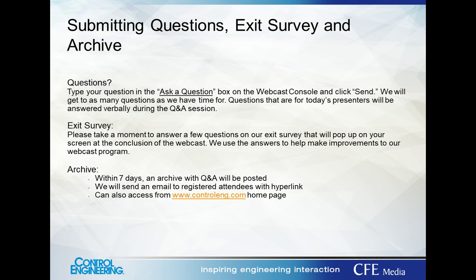And I think in industry in general, we found, especially in single loop control, and I kind of mentioned this on one of the slides earlier, that actually turns out to be not that common. And that's one of the burdens we created for ourselves with MPC, is we use 100% models. Not only is model-based control feed-forward, they use it 100%, you might say, at every matrix location. But that all comes with maintenance. So anyhow, in single loop world, feed-forward applications will find you.